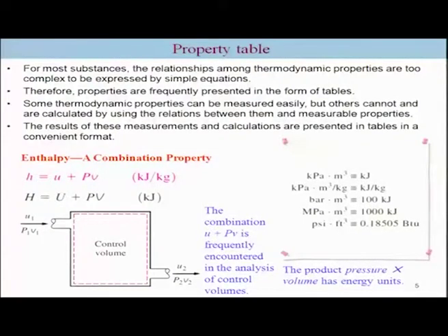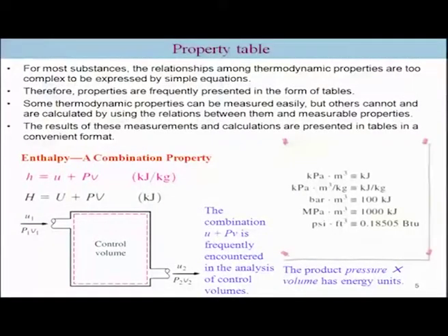So as I said, our intention is to have some kind of equation of state, but many times we fail, and for complex molecules it is extremely difficult to have a formulation with a function or an equation which relates PVT for all conditions, and thus the property table is more popular for very commonly used fluids such as water, refrigerant. So therefore, the properties are frequently presented in the form of tables.